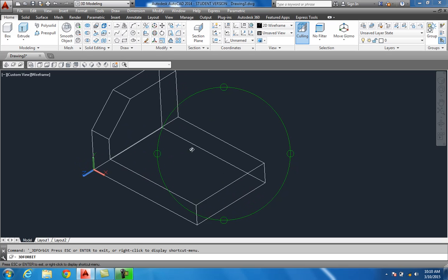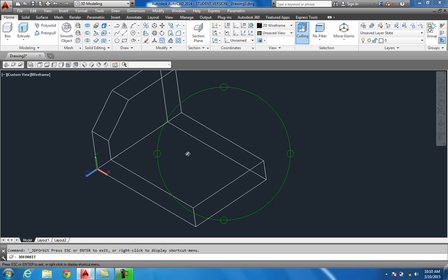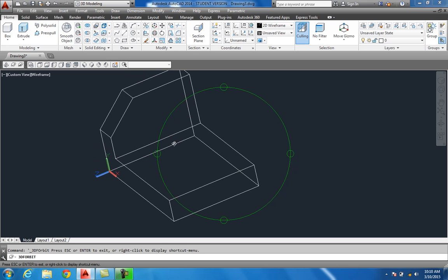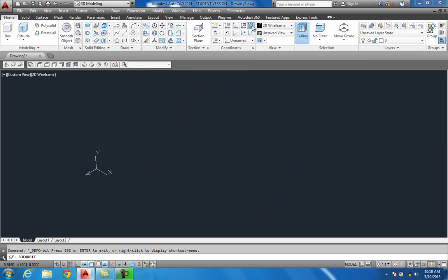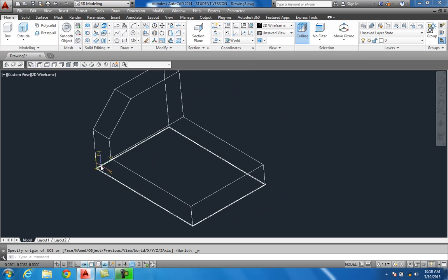And the only thing you got left up here is going to be pretty simple. We just got to go back to our world coordinate, hit world, switches it all back to the right direction. X this way, Y and Z. And what I could do is really and truly, I could just explode this and just do an offset of 1/2 of an inch.